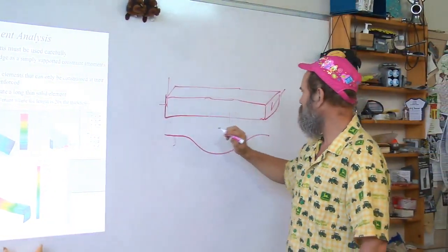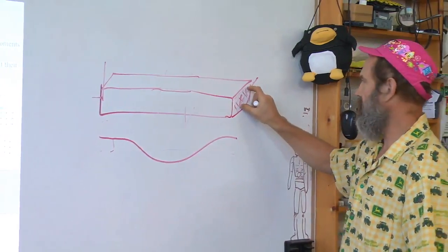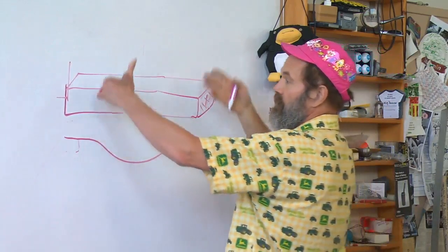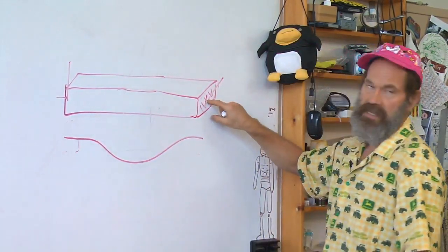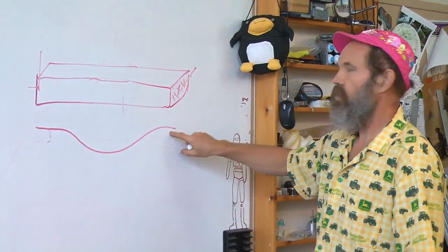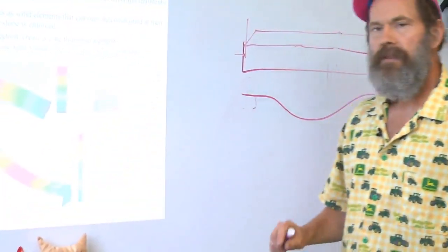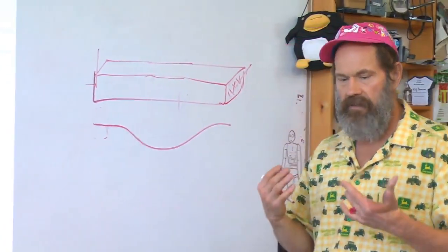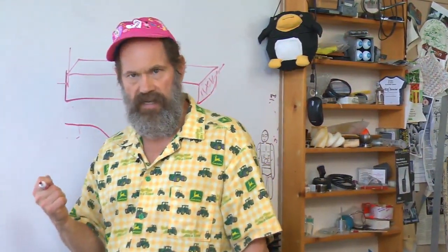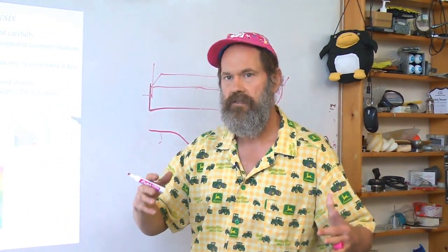In other words, if you check a surface to be constrained on a solid, it doesn't allow any rotation, even though you know when you're putting your beam in your machine, it's not being held infinitely rigid. So this is wrong. The beam is not going to bend like this. It's okay when you're designing your layout and you know you're going to be doing finite element analysis. Remember, you want to visualize the structure and how it deforms, what it does.